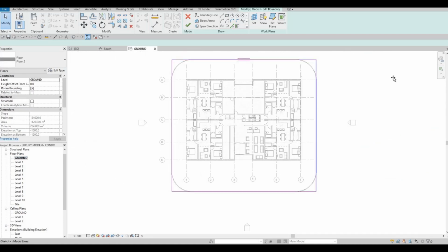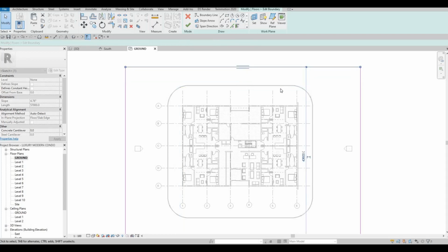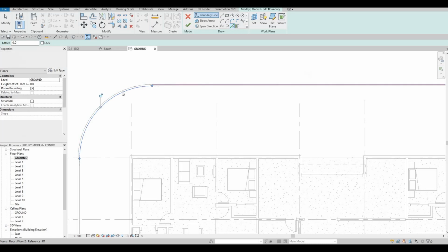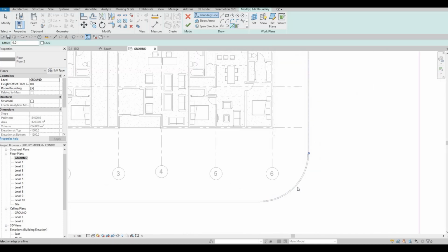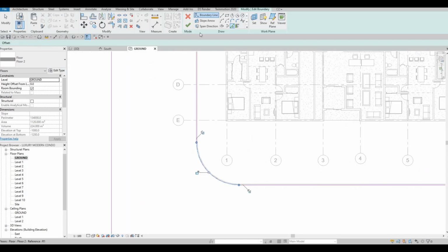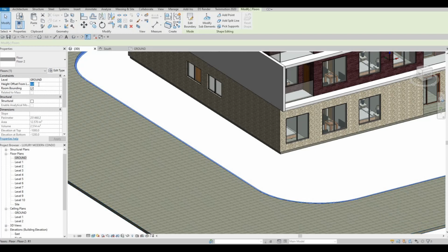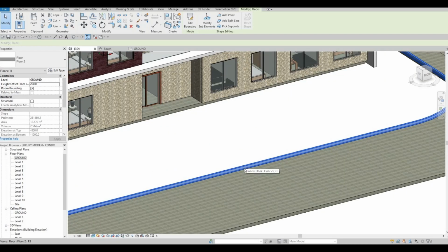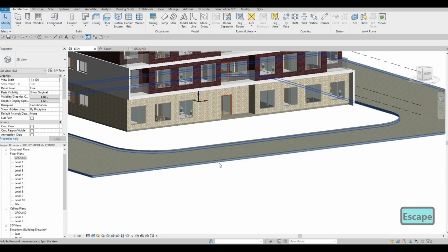Go right here. We can widen this now, because this still is the ground floor. But in order for this one not to be overlapping, what we need to do is to make a hole. Click finish, and then here at 3D we need to offset this to 200 to have that one there. And then of course we could just edit this later on. So here make it maybe just 100 or 50 if it's too high. I think 100 is perfect.